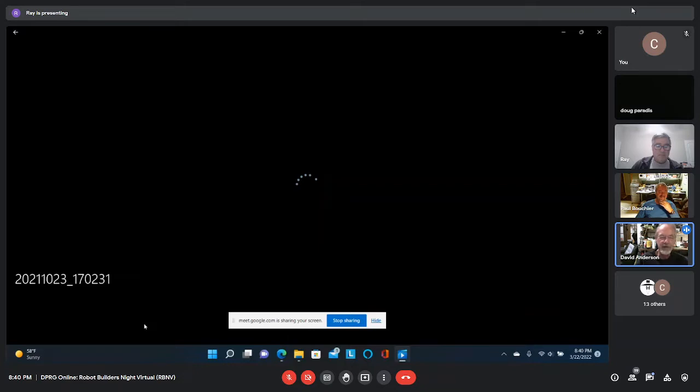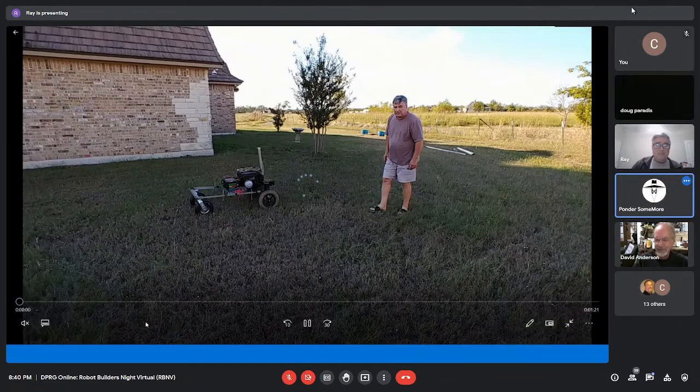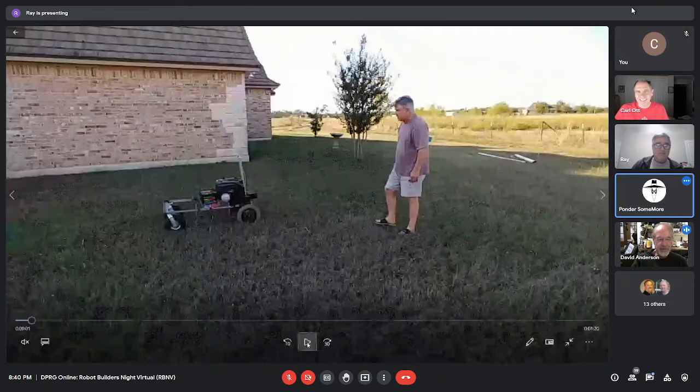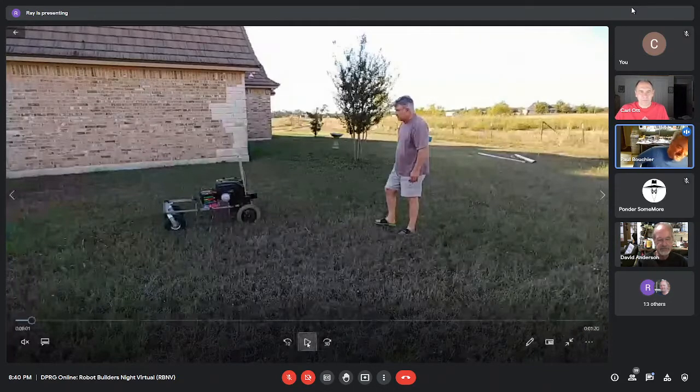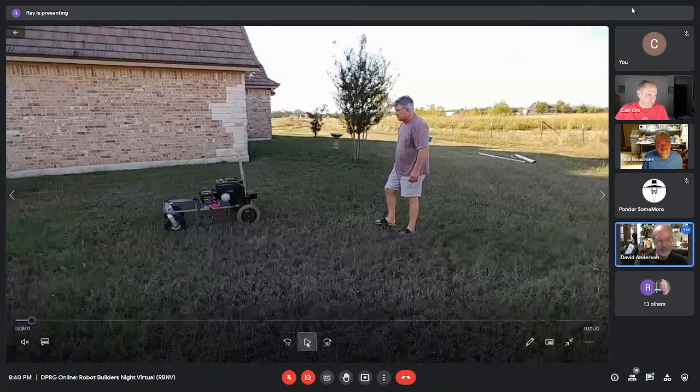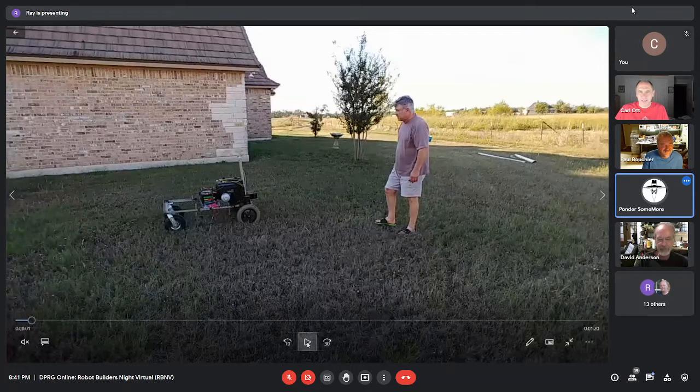But it may work on submarines because of the medium they're in and the kind of motion they do. Well, they're not using MEMS gyros either. The problem may be simplified when you're in the water, and they have better accelerometers. Yes, you have to go to a completely different accelerometer technology. MEMS gyros are junk. They're good for really coarse signals, but the error rate is huge, and it's accumulative when you're integrating.